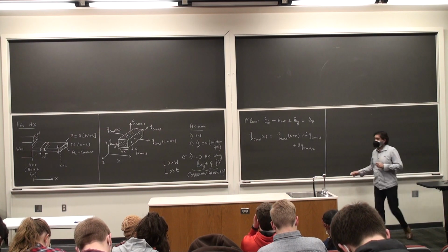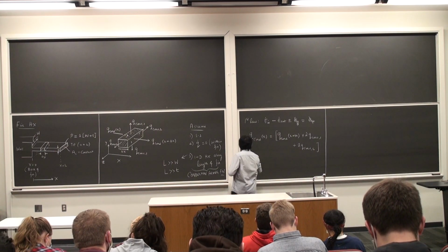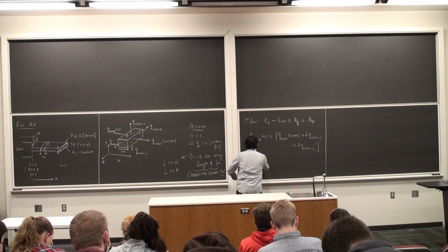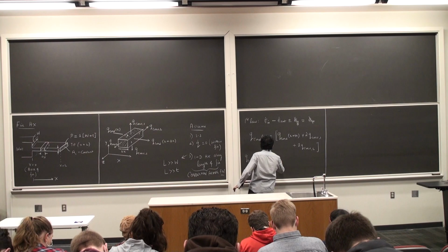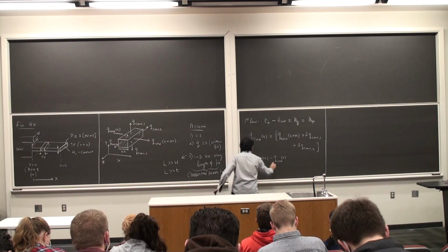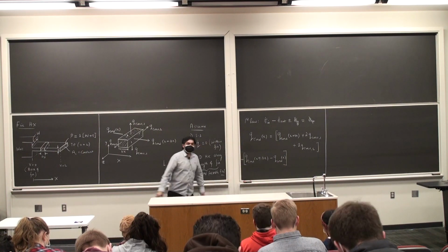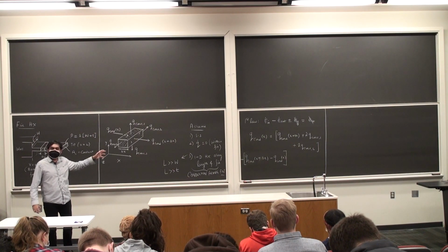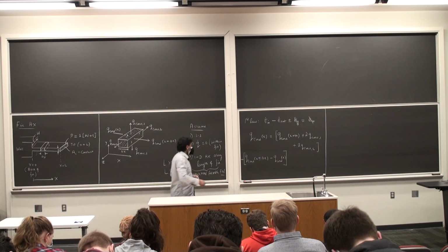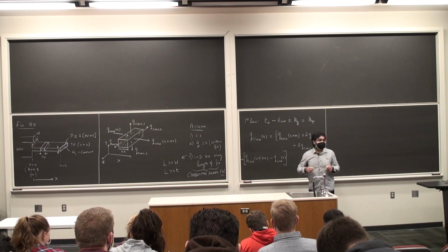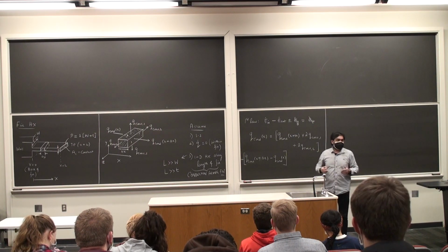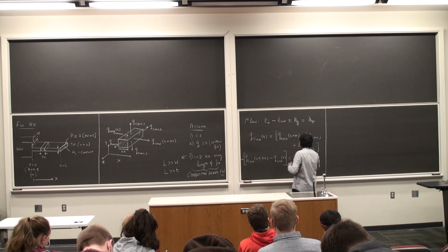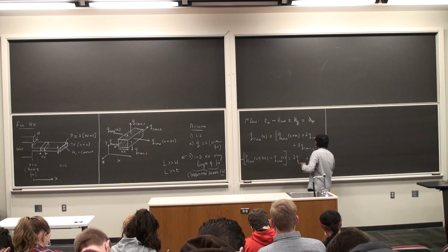I'm going to rearrange this and now bring in the fluxes. So this is Q conduction x plus delta x, minus Q conduction x, with a negative sign. I'm essentially bringing the Q conduction x plus delta x onto the left hand side and rearranging so that I have a negative sign, and then x plus delta x minus x. You can immediately recognize we're going to take the limit of delta x tending to 0. And this will eventually give me a partial derivative with respect to x. And this is 2 times Q convection 1, 2 times Q convection 2.